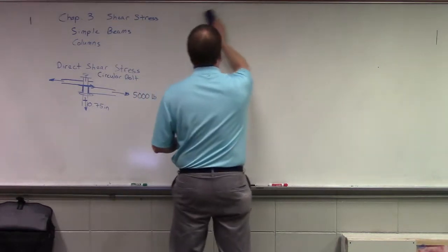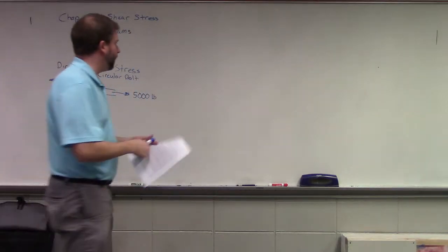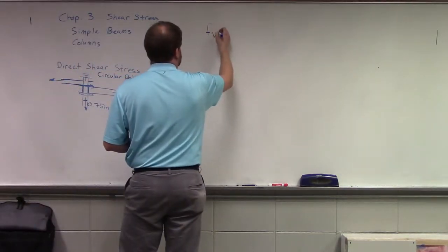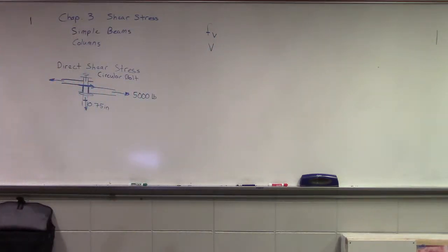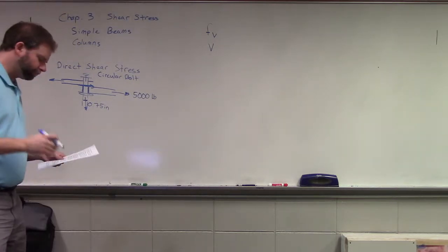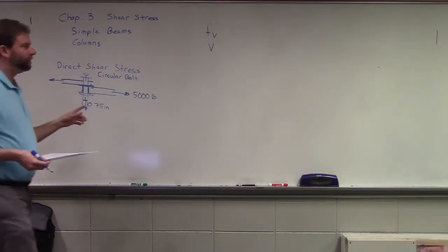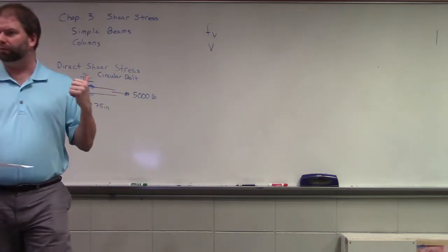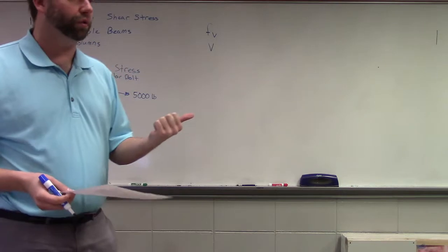We want to remember that when we are performing shear calculations, we use either the notation V sub V or V for our shear stresses. V is the letter used to denote shear investigation. As we're looking at these beams, we will again assume that the self-weight of the beam is negligible and we don't need to take it into account as we're doing this investigation.